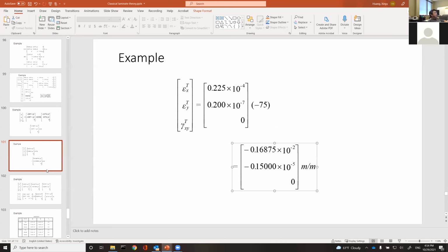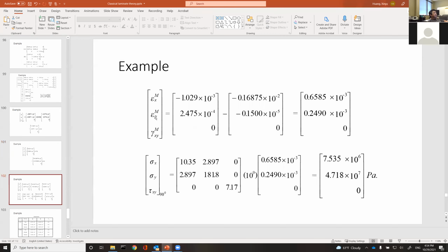All right. We also know that the total strain is thermal strain plus mechanical strain. So we can figure out the mechanical strain. Mechanical strain will be total strain minus thermal strain, because mechanical plus thermal is total. If you know the total and the thermal, you subtract thermal out of the total, you get mechanical. And the mechanical strain is what causes stress. Only mechanical strain is related to mechanical stress. Thermal strain is due to temperature change, so it is not related to stress.